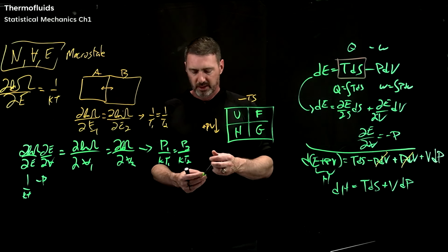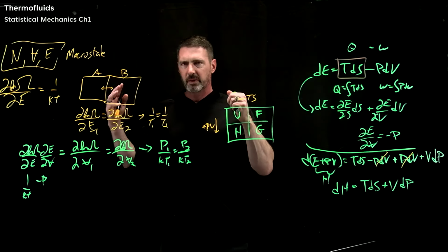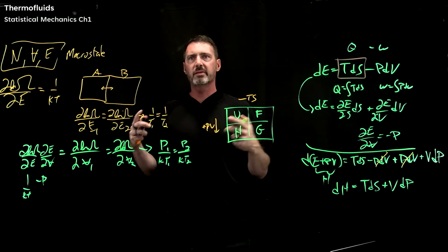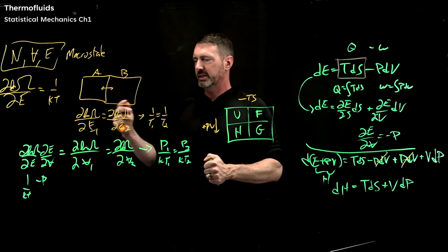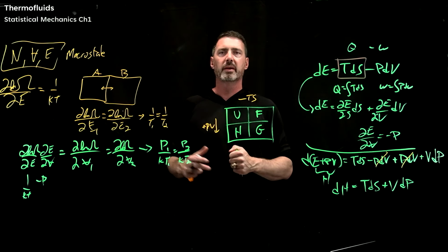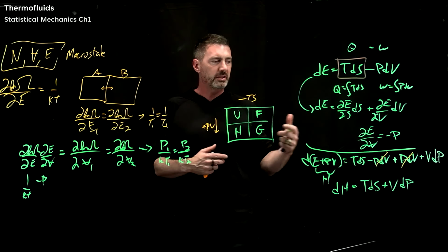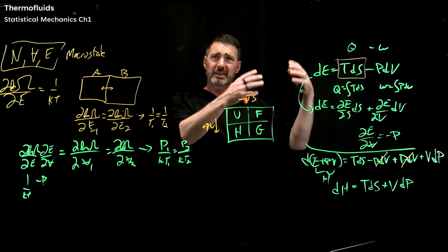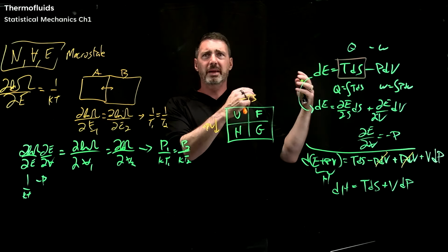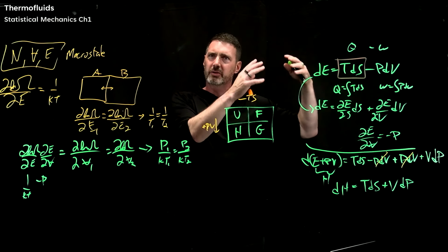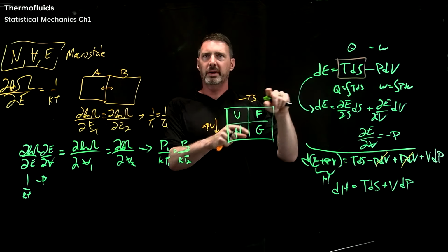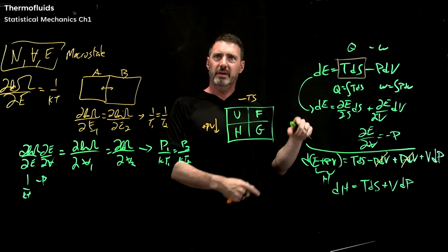And really some of the reason I like going through this math, or actually fully believe that you have enough math in undergrad that this is nothing crazy, is because if you understand where some of this math is coming from, and you have the right tool, then step one in solving any thermodynamic problem is listing out your assumptions. Like, well, what is being held constant? Do I have any heat? You're just listing out your assumptions, and then after you've listed them out, you're free, if you will, to choose your own adventure to solve the problem by the easiest means possible.